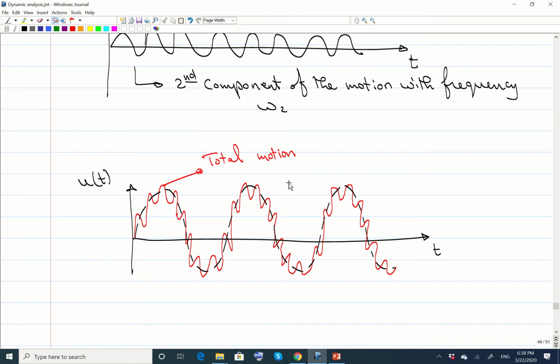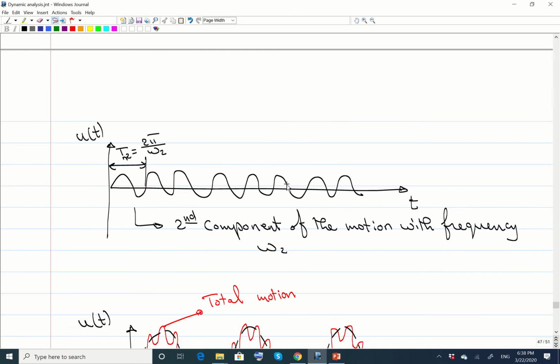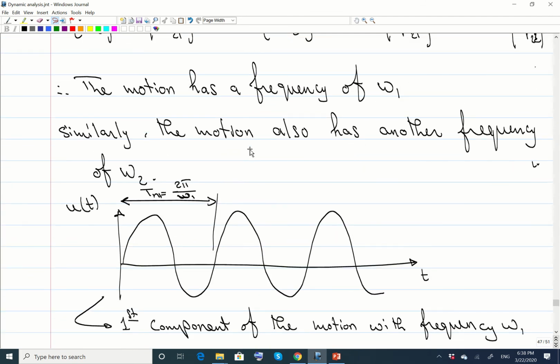Now, if you go through chapter 13, we're not going to do this, but for structures you have to add all the components of those modes, okay? If you have a 40-story building, you're going to have 40 modes of vibration, okay? Omega 1, omega 2, omega 3, and so on until omega 40, okay? But only the lowest frequencies are going to contribute the highest to the motion, the amplitude of the motion.